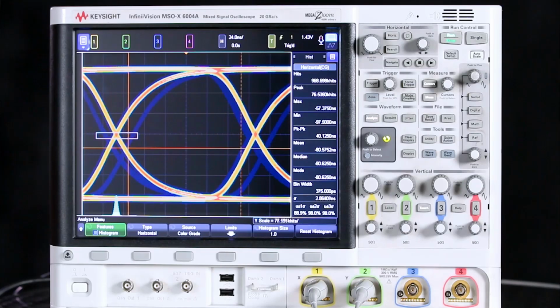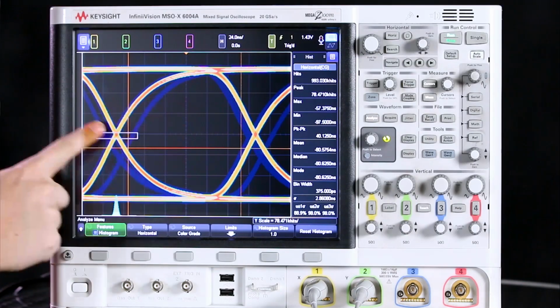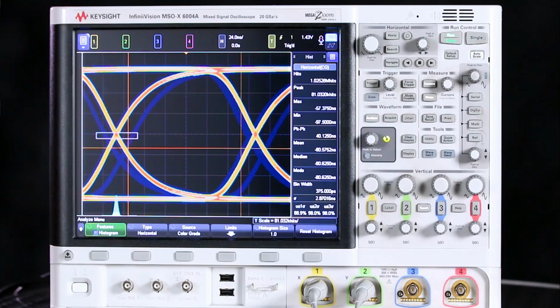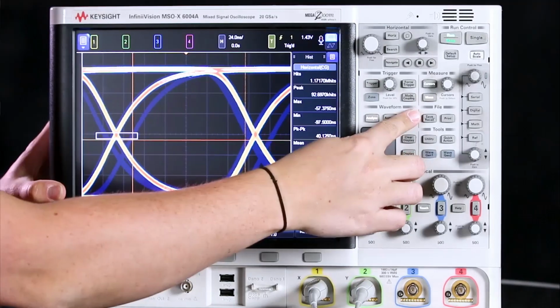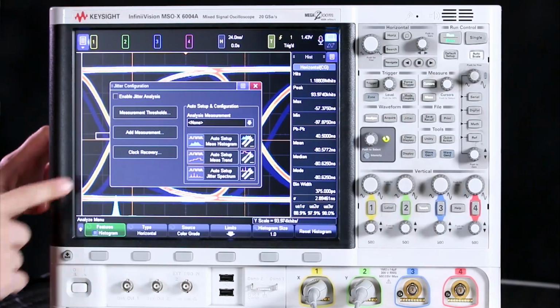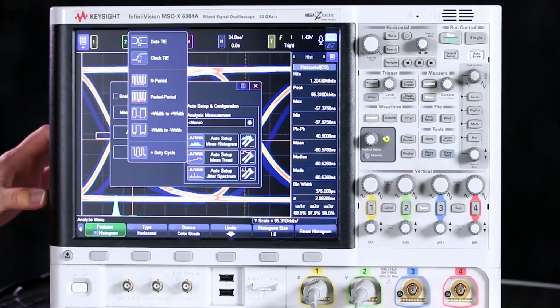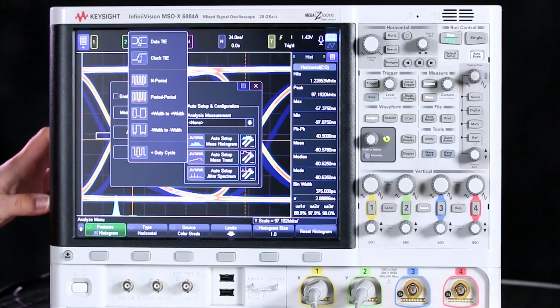If you're seeing very bad random jitter that will cause errors in the data you transmit, kind of like we're seeing on the signal here, you might have to actually go back and redesign that component. And if you want to learn a little bit more about some of the other jitter measurements available, be sure to check out the 2-Minute Guru episode on basic jitter measurements. Daniel talks a little bit more in depth about a few of the other measurements.